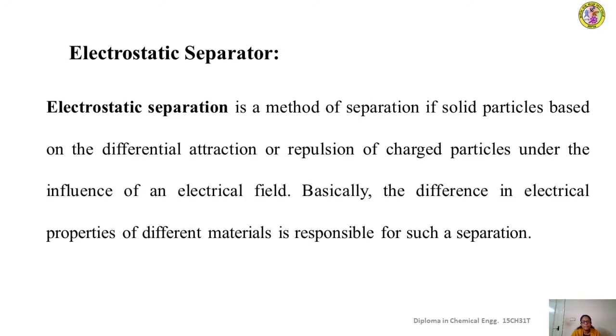So electrostatic separation is that method of separation of solid particles based upon the difference in the attraction or repulsion of charged particles under the influence of an electric field. So we need to create an electrical field, and in that field the different particles based upon their different surface charges will behave differently. So either they are attracted towards the electrical field or they are repelled from the electrical field. So this difference of electrical characteristics of the particles is utilized to separate different particles of different materials from the given mixture of solid particles.